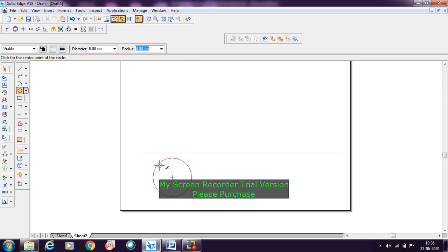In order to get the points on the circumference, we need to divide the circle into an even number of parts. You can divide the circle into 2, 4, 6, 8, 10, or 12 equal parts. But when I take 4 equal divisions, it will be difficult to identify the points. So for that reason, I will be dividing the circle into 8 equal parts.